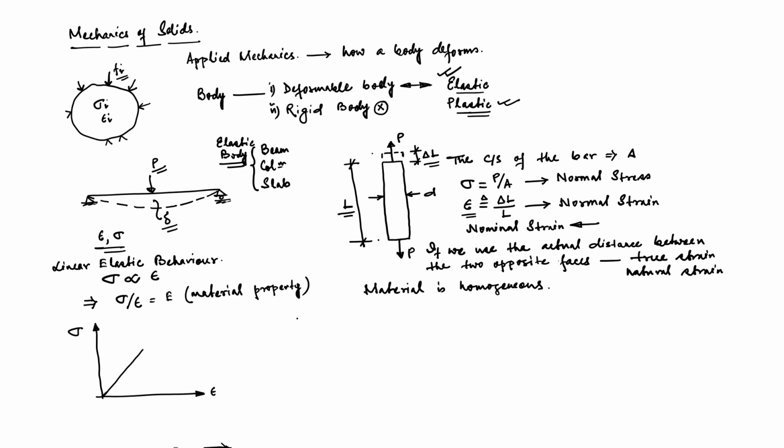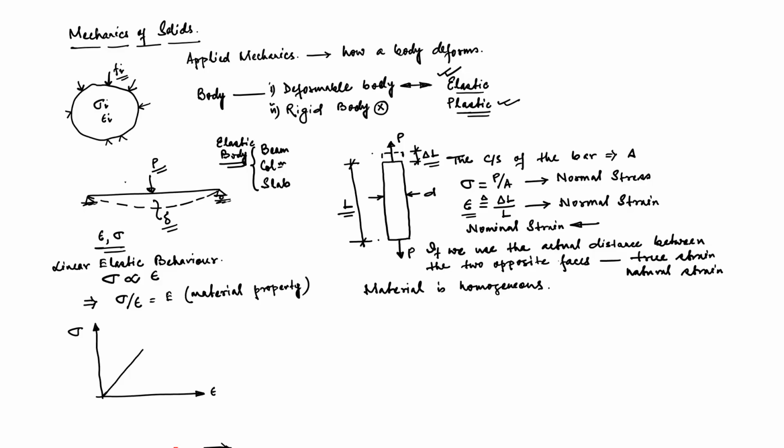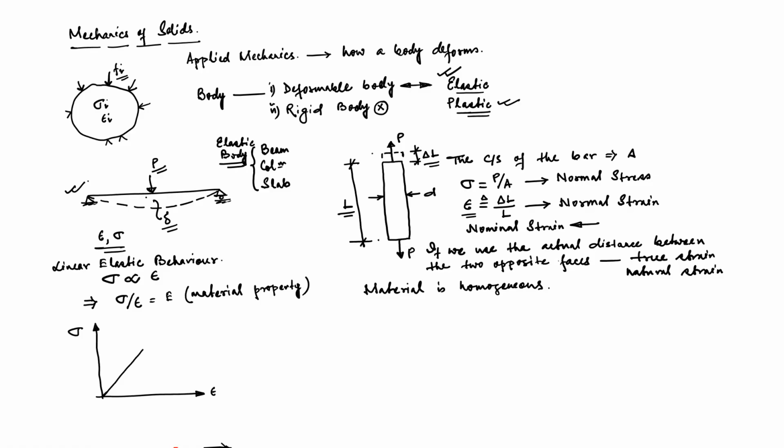but in both the cases, the moment we apply some external force, there will be internal deformation, and the moment there is an internal deformation, that will develop strain and subsequently stress. And in fact, when you go to design this structure, for example, say this beam, under the action of this load P, what we do at different sections, we evaluate how much stress is developed, and then we select a material, so that the material along with the cross section of the beam can withstand that applied stress.